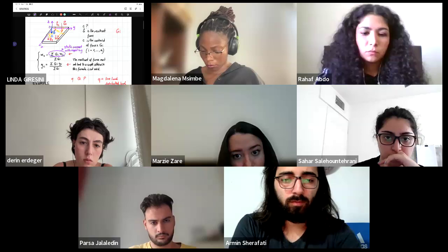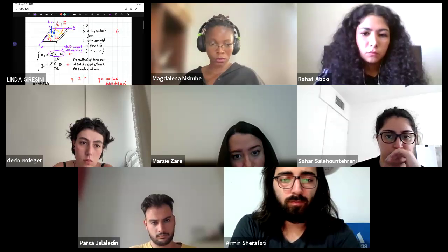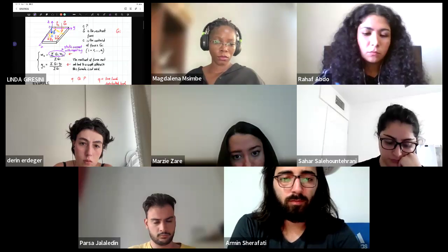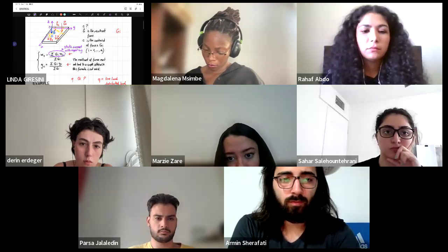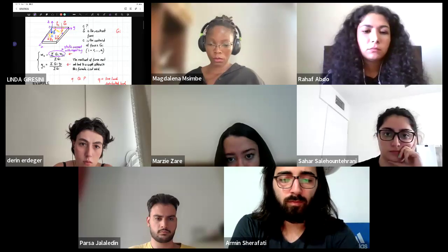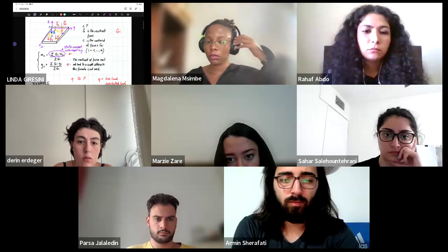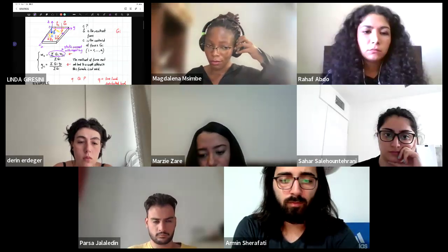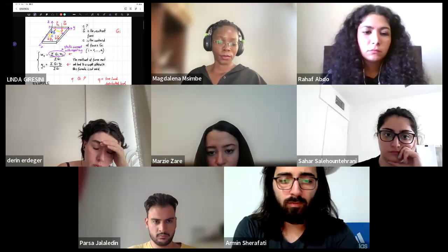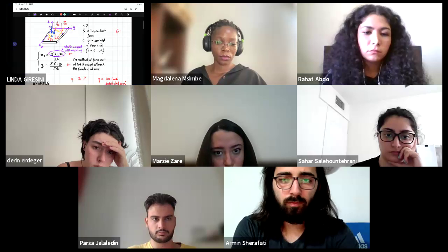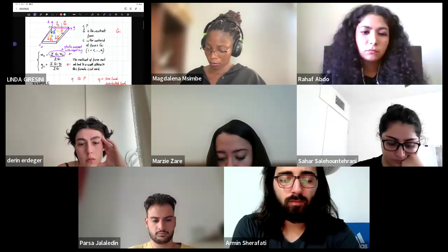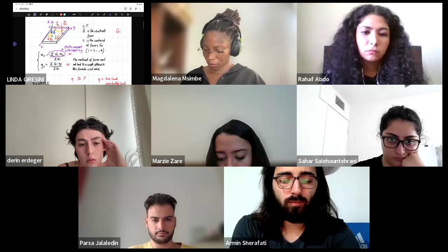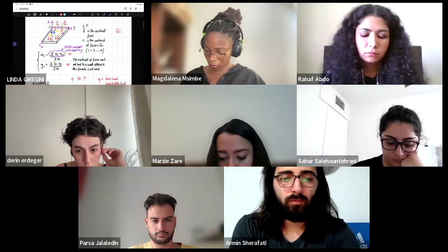Why with respect to y? Because x is the distance of a generic point from the y-axis. You see here, for example, the generic distance xi, this one, is the distance from the y-axis. So this sum of Gi times xi is the static moment of the Gi forces with respect to the y-axis, because xi is the distance from y. Because the distance of any point from y is measured through xi.